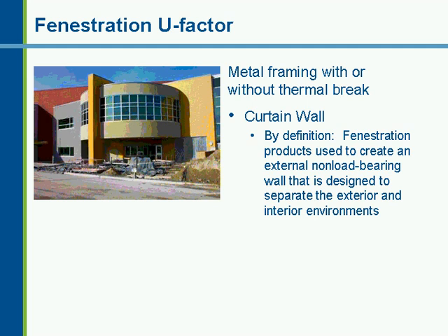Site-built products have always been kind of a problem from a documentation standpoint. Site-built products have to be rated by the National Fenestration Rating Council, and sometimes it's hard to find the NFRC rating on these particular products, and there's never really been a clear distinction between the different types of site-built window products. The new code actually does try to split the differences on here.